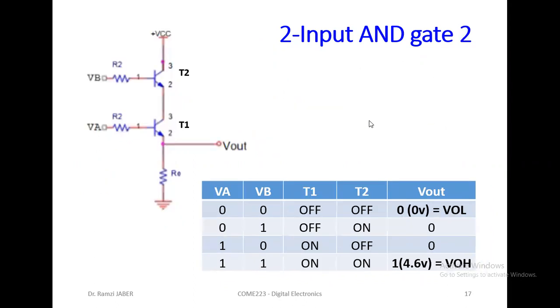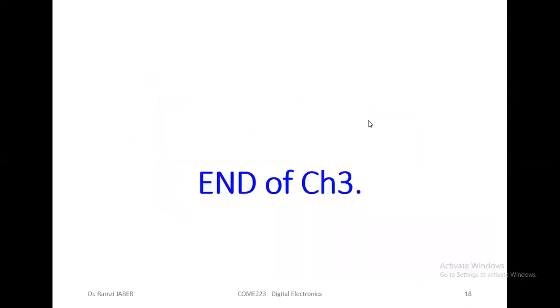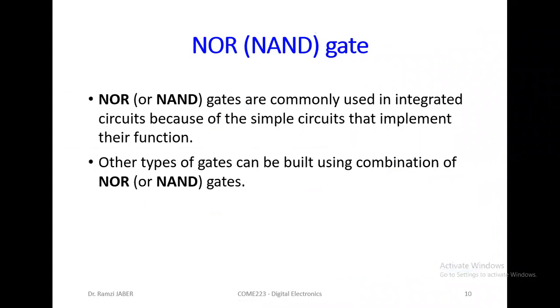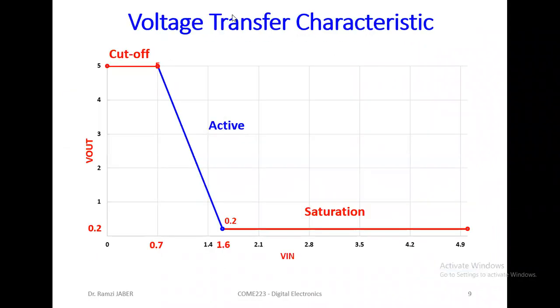Okay, so the BJT does not give us the optimal solution. The chapter is finished. In chapter 3 we understand that the BJT is not used for digital electronics. Understand this, the summary of this chapter: the RTL BJT is not recommended to be used in digital electronics, but it can be used in analog circuits because they have an active region, a big active region. In active mode or linear mode, which is amplifier mode, which is not for digital electronics.